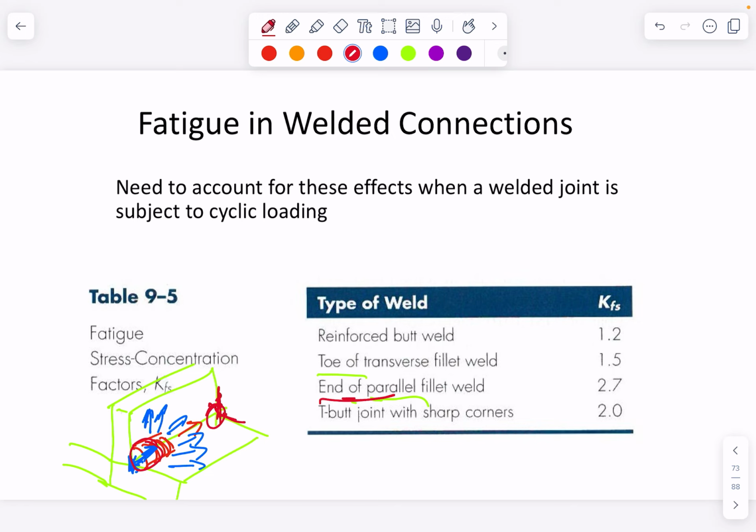So there's all sorts of things that you need to be thinking about. And in fact, the other way to deal with this is if you've got, say, 100 millimetres of weld, and it might be a 6 millimetre weld, then you ignore the first couple of diameters on each side. So that becomes effectively, say, like an 85 millimetre weld that you do your analysis on.